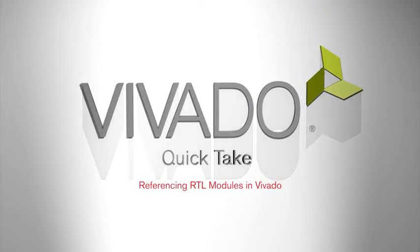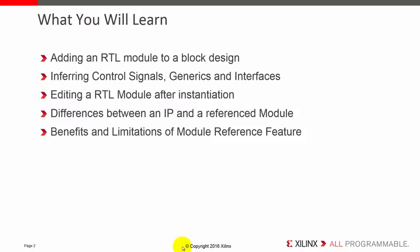The module reference feature of the Vivado IP Integrator lets you quickly add a module or entity definition from a Verilog or VHDL source file directly into your block design. While this feature does have limitations, it provides a means of quickly adding RTL modules without having to go through the process of packaging the RTL as an IP to be added through the Vivado IP catalog.